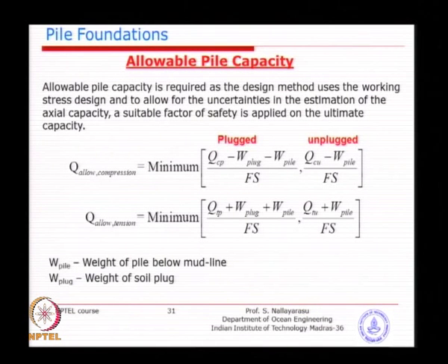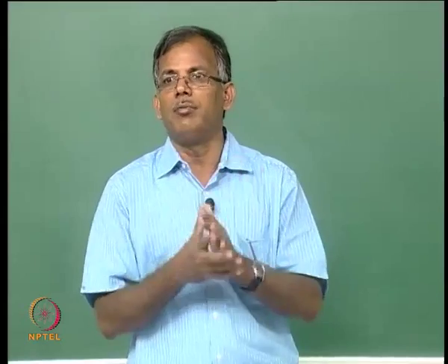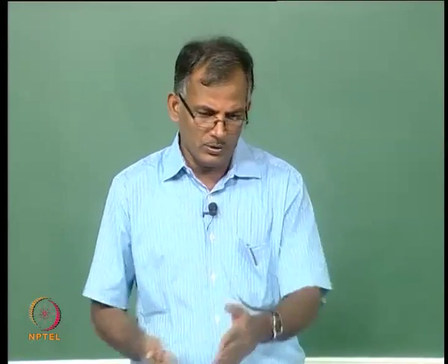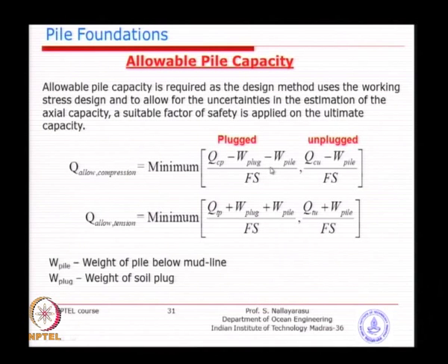For example, instead of a tubular pile, if you have a solid concrete pile, what happens? The material of the concrete in the pile itself is becoming part of the load. So, that is exactly it: in the plugged case, the weight of the pile plus the weight of the soil must be taken out of the capacity for the buried portion. Of course, the portion above the seabed is anyway part of the load, because you are analyzing the jacket structure.